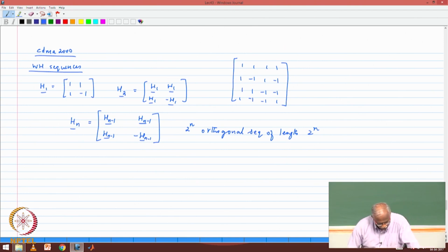Okay, so what we look at is the cross correlation. If you look at these two sequences, just as an illustrative example, they are orthogonal, but if you shift them by 1, what do you get? If you shift them by 1, basically do a circular shift, you get perfect correlation. You get correlation of 4. I mean, this is worse than different M sequences, no? Because basically it gave you as if you are doing perfectly aligned.